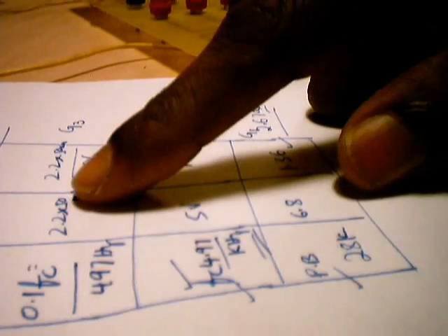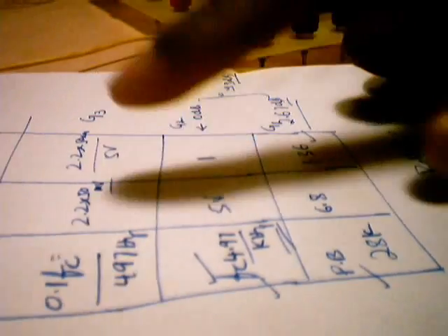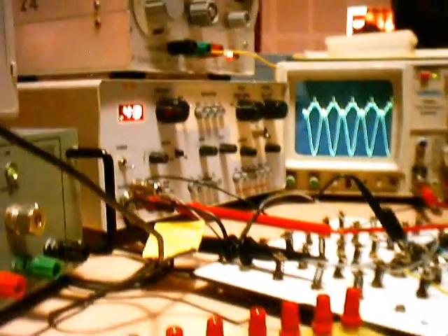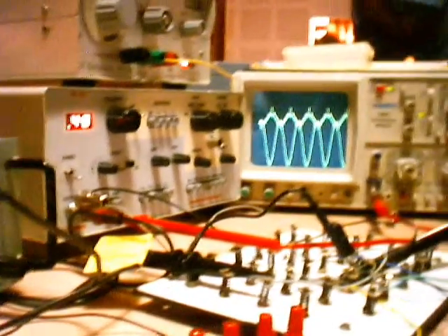You find out the output voltage. Before you measure the output voltage, ensure that input is kept at 5 volt peak to peak. You should always use a signal generator which has low output impedance, which ensures that there is no loading effect on your signal generator.